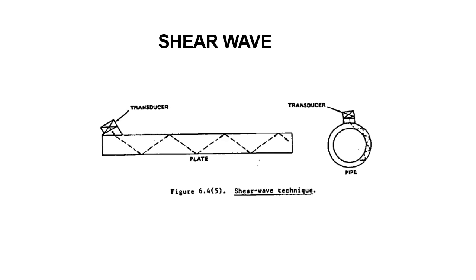To reduce confusion from dead zone and near zone effects encountered with straight beam transducers, parts with a thickness less than 5/8 of an inch are tested with angle beam units. In this technique, the beam enters the test material at an angle and proceeds by successive zigzagging deflections from the specimen boundaries until it is interrupted by a discontinuity or a boundary where the beam reverses direction and is reflected back to the transducer. Allowances are made when placing the angle beam unit to account for the lessened effective length of the penetration because of the zigzag path taken by the beam.